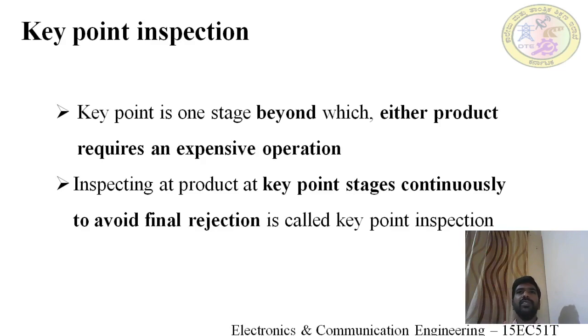Key point is the one stage after which the product requires an expensive operation. Inspecting the product at the key point stage continuously to avoid final rejection is called key point inspection. It will avoid final rejection.